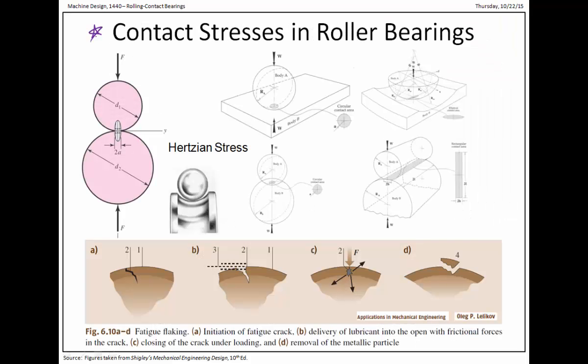The fundamental engineering that's going on beneath the surface, so to speak, because that's sort of a pun, is this contact stress, which we spoke on a little bit. I pointed out that if we took a little pencil and pressed it against the desk right here, and we looked really closely, the area at the interface would be infinitesimally small, which would make the stress skyrocket, infinitely large. We know that can't be, so there's got to be something else going on, and that's going to be local deformation. It could be very local stresses, but it's mostly going to be deformation that takes it up.